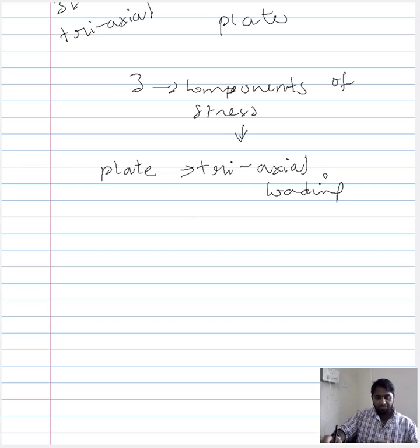Even though this is a three-dimensional plate, given its size or its characteristic dimension, the number of components required to describe the mechanical condition experienced by a region within this plate is just 3. So we saw that when we want to describe the mechanical condition experienced by a specific region in a three-dimensional material experiencing triaxial loading, we needed 9 components, and we were able to identify some relation between the shear stress components, and reduce those 9 components to 6 independent components.